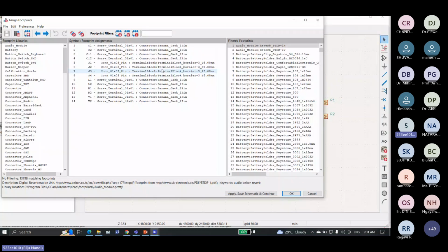We have to focus on the footprint, because if your footprint is incorrect, you won't be able to solder. We are able to solder your equipment, meaning any capacitor, resistance, IC, anything. You have to design your footprint correctly.